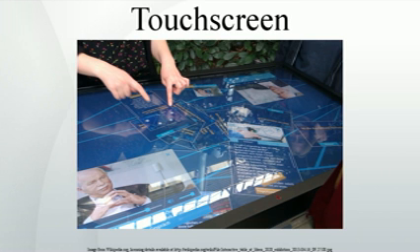Mutual capacitance. This is the common PCT approach, which makes use of the fact that most conductive objects are able to hold a charge if they are very close together. In mutual capacitive sensors, there is a capacitor at every intersection of each row and each column. A 16 by 14 array, for example, would have 224 independent capacitors. A voltage is applied to the rows or columns.